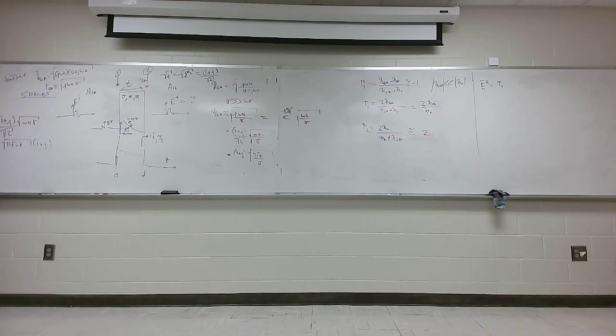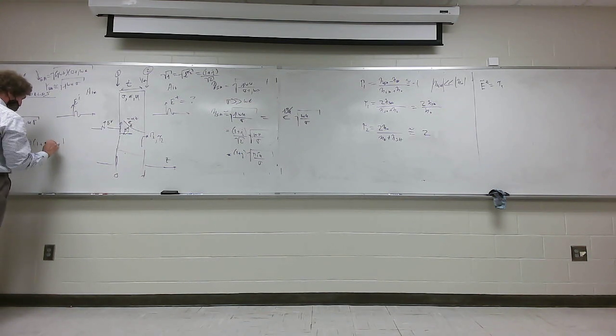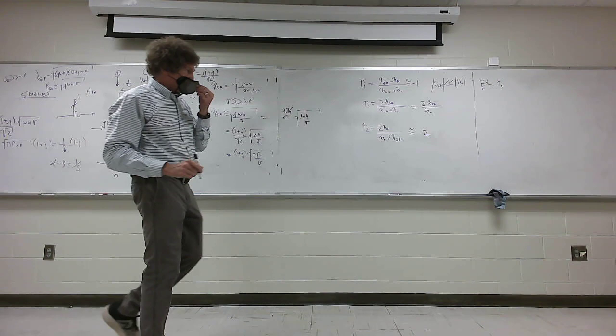The reason I did this is, anybody remember what is 1 over the square root of pi f mu sigma? Anyone? Skin depth, remember? Skin depth was equal to 1 over the square root of pi f mu sigma. So I can rewrite this, and it's written this way a lot of times. It's just 1 over the skin depth times 1 plus j. And that means alpha in magnitude equals beta, which is equal to 1 over the skin depth. That's the only thing you take from that.